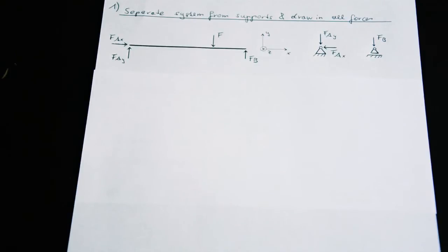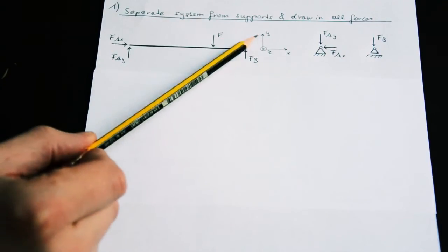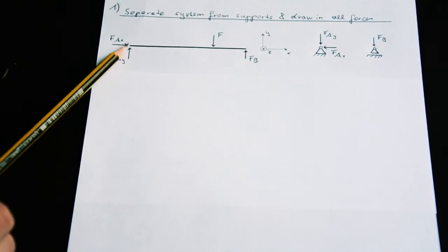Okay. We then get 3 parts, the beam on one hand and the 2 supports on the other hand. So in the beam we have 2 forces acting at point A, Fay and Fax, let's say, according to our coordinate system, x and y. There are 2 forces because there was the pin, which is able to support 2 reactions. As you should already know, the direction of Fay and Fax does not matter. They just have to be drawn in the opposite direction on the other part of the cut. This is the nature of internal forces. This is always the same.